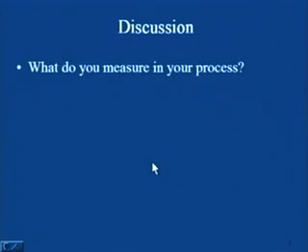Before we decide who is the better shot, let us see what we should do in our processes. Whenever we measure any characteristic of a process, we should know what we are going to measure. Suppose there is a shaft that you are turning on a lathe. Are you measuring the diameter of the shaft, or the eccentricity of the shaft, or the surface roughness of the shaft? First we need to be very clear about what we are going to measure in our processes.